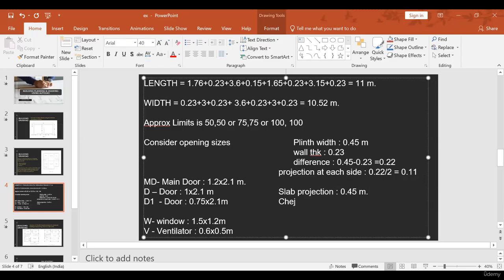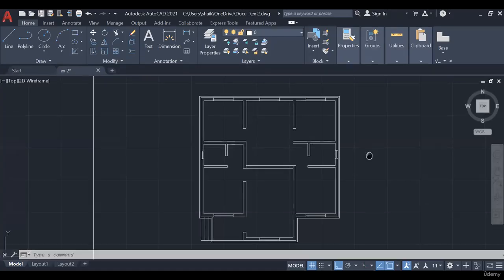If there is any object or some shortage of area, in those cases we can go for a lower one, but this is the minimum which we need to provide, 0.45 meter. Next one is Chhajja projection, that is 0.6 meter. I will draw the Chhajja projection quickly.